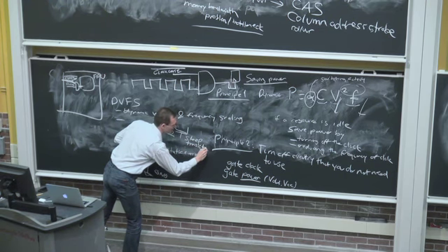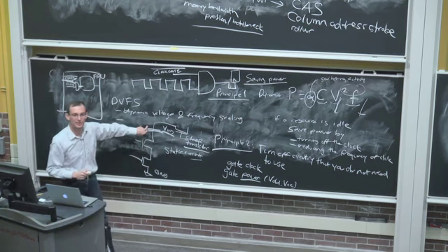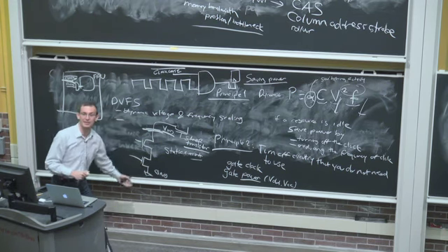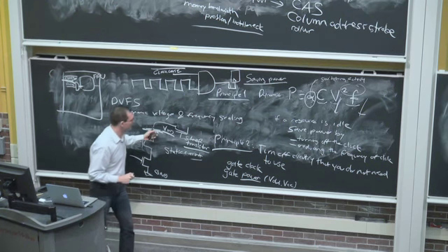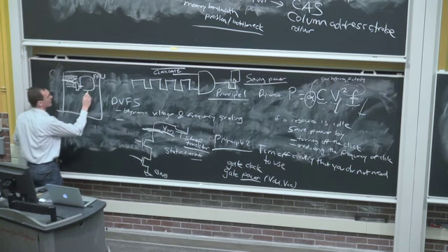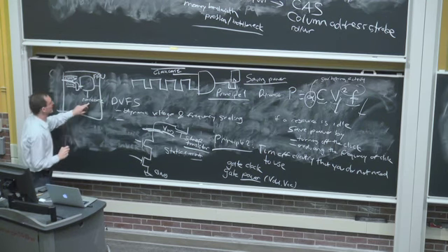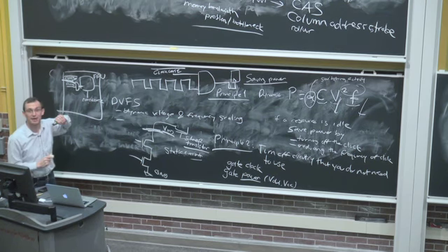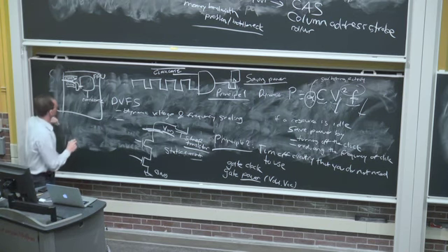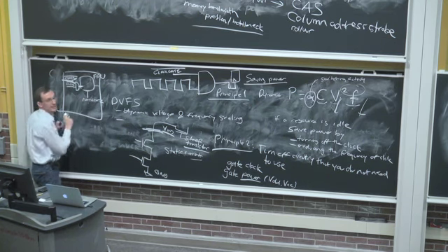In a sense, you put the circuit to sleep. If you enable that signal, the power is not supplied to the circuit, and now you cut down that leakage. So how do you do that? Well, if you know that you're not going to use this FPU, floating point unit, you have a signal that says also power gate. Now you can eliminate the static power as well as the dynamic power from the circuit. That way, essentially, you're cutting off any power that's consumed by the circuit.